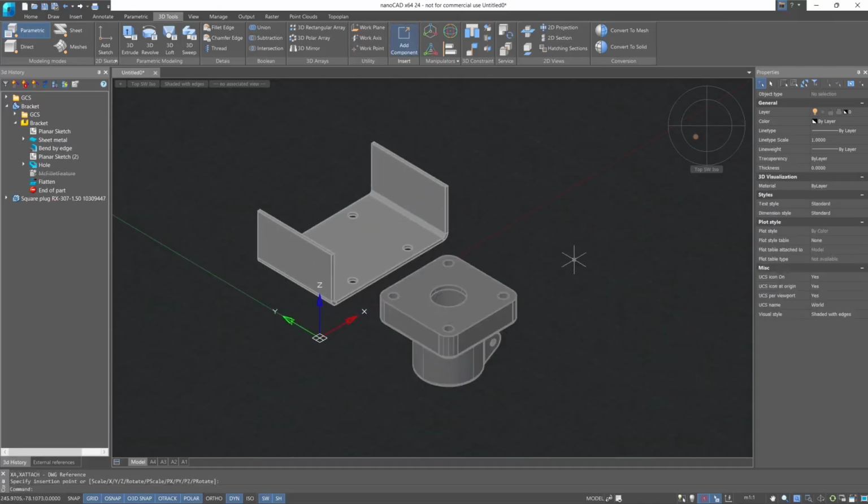When creating assemblies, it's recommended to fix one of the parts using the Fix command in the 3D history or by aligning it with standard planes and the 0 coordinates, which we'll discuss a little later. After adding all the required components, we may need to set their positions relative to each other using 3D constraints. We'll explore this a bit later. Right now, we'll look at how to change the position of an assembly or part in space using manipulation commands.